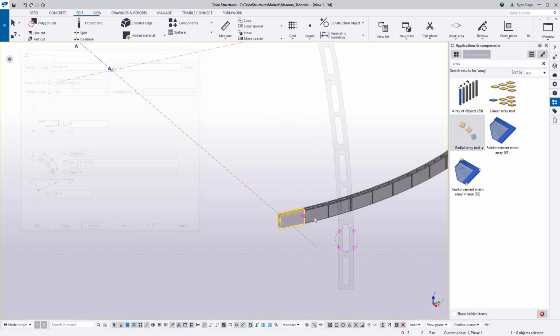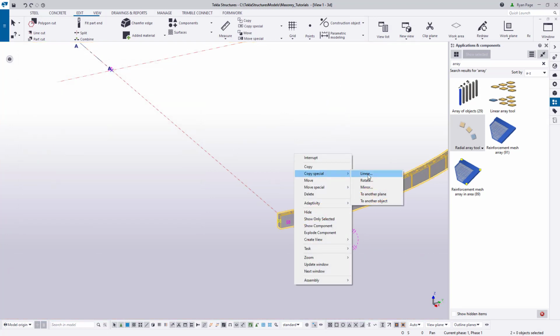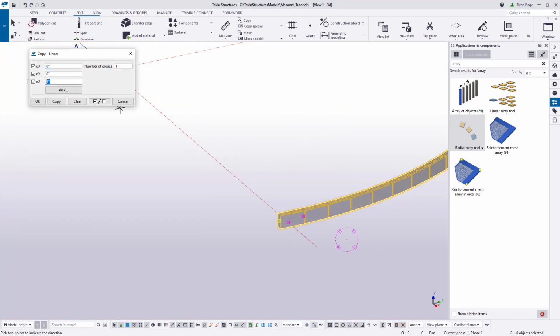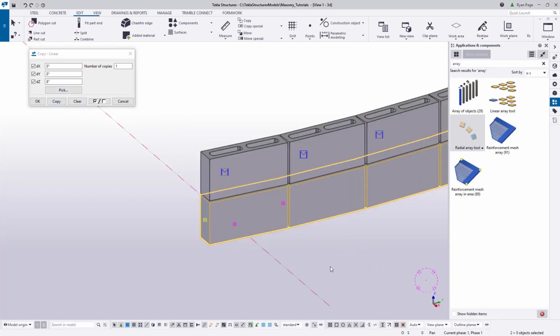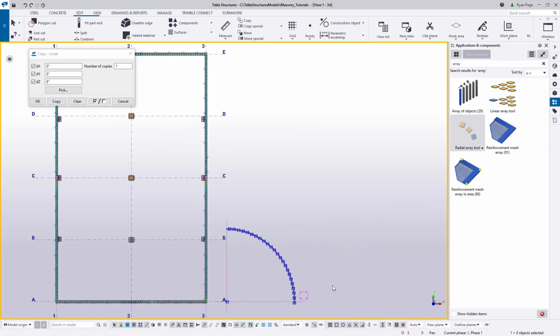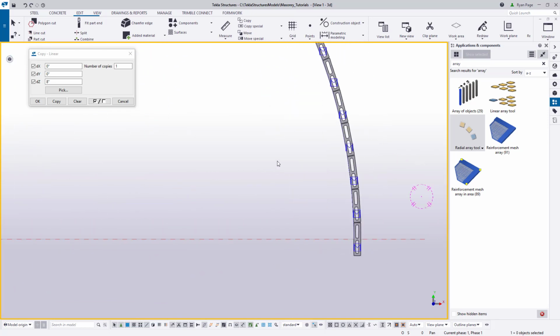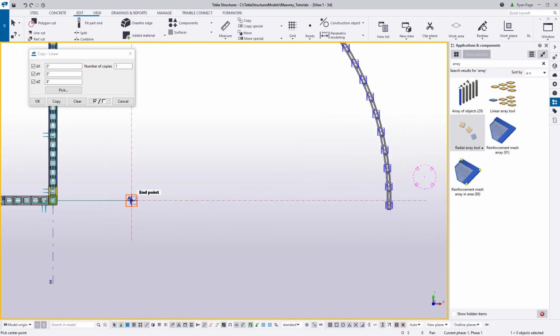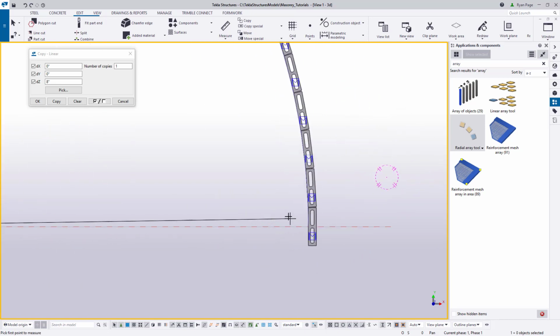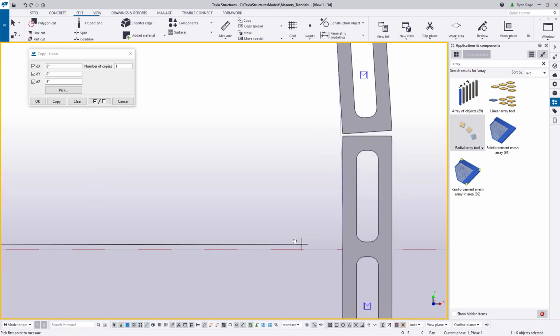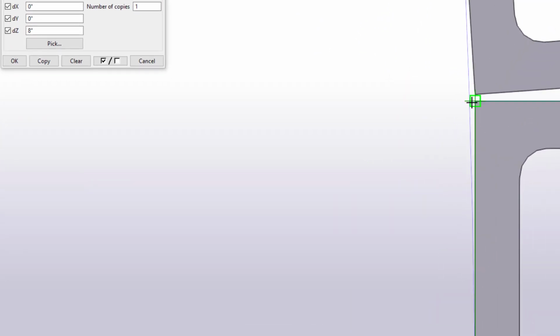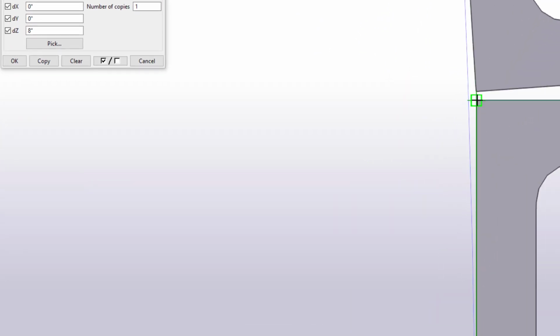Now, we can form our additional courses as we have been in the past. We can copy the original block upwards 8 inches and notice how the array also comes with it. Next, let's rotate the second course so the bond sits correctly. Now, we can use the Measure Angle tool to get the angle of rotation we're going to need. And once we have that, we can use the Move Rotate command with that angle to nudge the second course a half block's length in the counterclockwise direction.